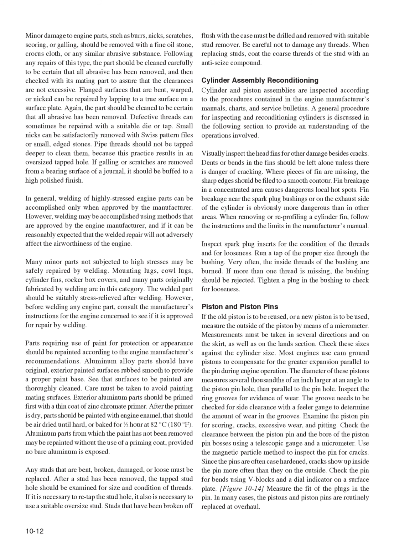If galling or scratches are removed from a bearing surface of a journal, it should be buffed to a high polished finish. In general, welding of highly stressed engine parts can be accomplished only when approved by the manufacturer. However, welding may be accomplished using methods that are approved by the engine manufacturer, and if it can be reasonably expected that the welded repair will not adversely affect the airworthiness of the engine.